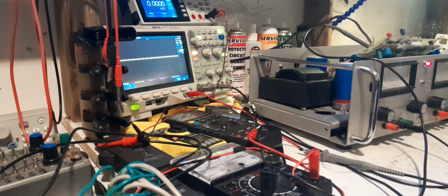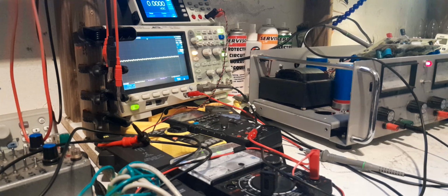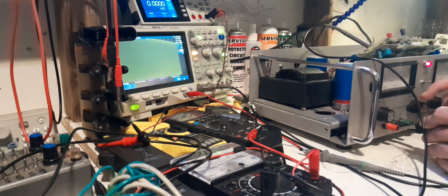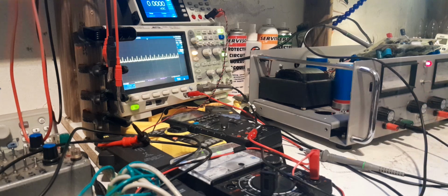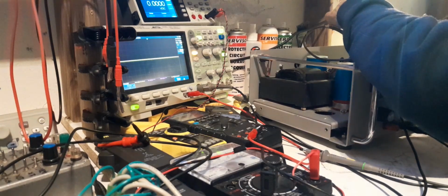that's the constant current op amp. Put a load on it. Hey! Bloody cats. Ooh, straight into oscillation. Same thing, right? So we'll put 100 nano and 1K from the output to the input on the constant current op amp.